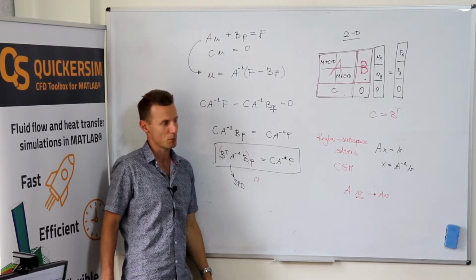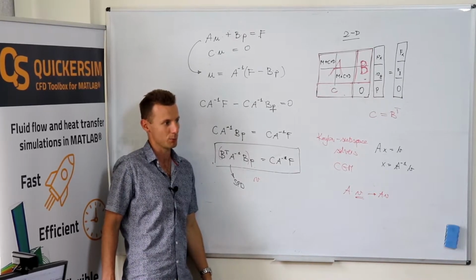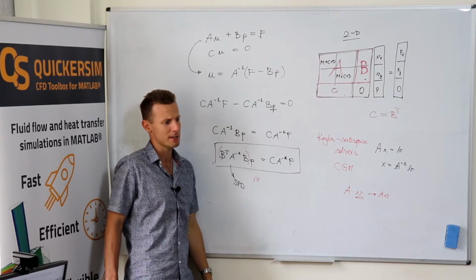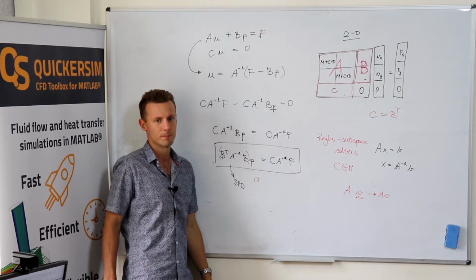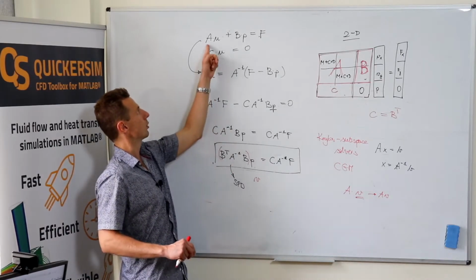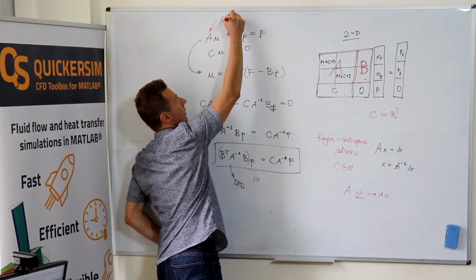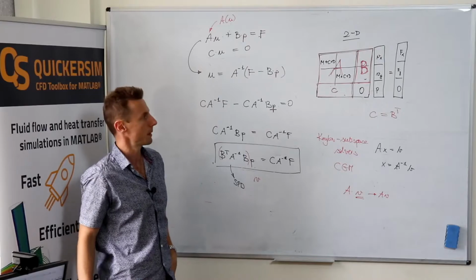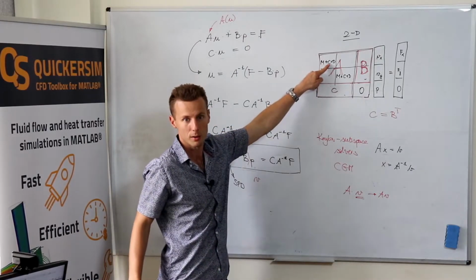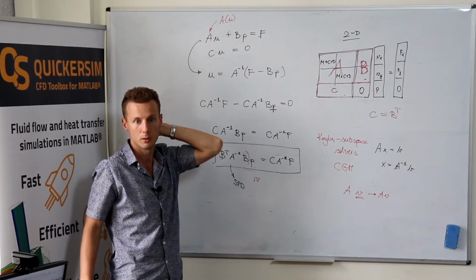It works. For small problems, you can write such a code. Nice numerical example. I think it's even in one of our CFD Toolbox tutorials. What is nonlinear? Nonlinear is that, if you've got Navier-Stokes, then the matrix depends on u because the convective term depends on u.